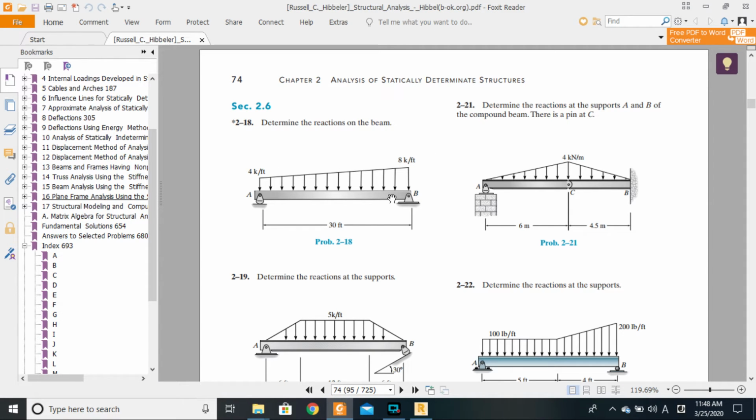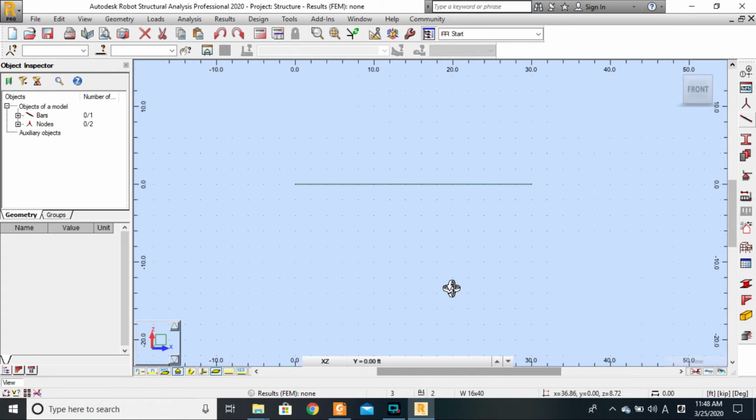Going back, what's the next thing we want to represent? Maybe the loading, the trapezoidal load, right? For that, you will need to come right here and define a particular load type first, because in structural analysis we may just define loads and use them as they are. But in reality, when you're dealing with real structures, you have different types of loads.